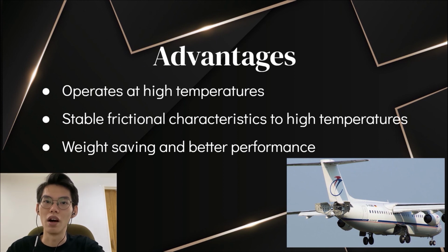Aircraft brakes made from carbon-carbon composite are relatively lighter than brakes made of steel. The carbon-carbon composite brakes weigh 30 kg compared to 100 kg for brakes made of steel, and carbon-carbon composite was found to be 3 to 5 times better than steel brakes in actual number of landings before burning out. Thus, carbon-carbon composite brakes provide more than weight saving alone and perform better.